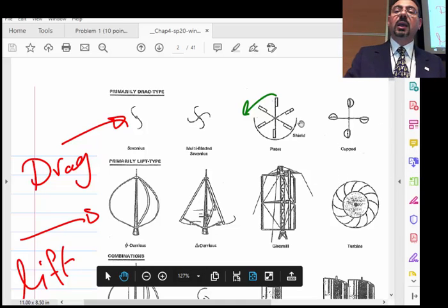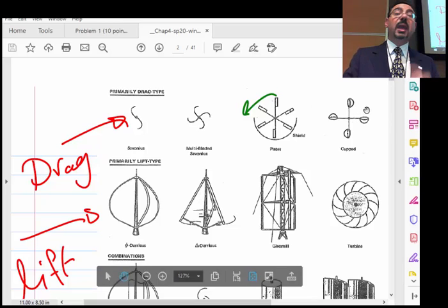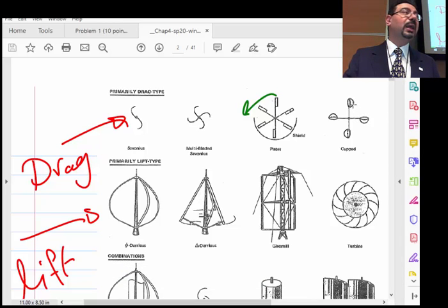But the point is, it's depending on the drag, and therefore what is the maximum velocity of that plate rotating around the X? Its maximum velocity would be the wind speed. It can never reach a speed faster than the wind pushing on it. Okay? Is that unique to drag-based machines?